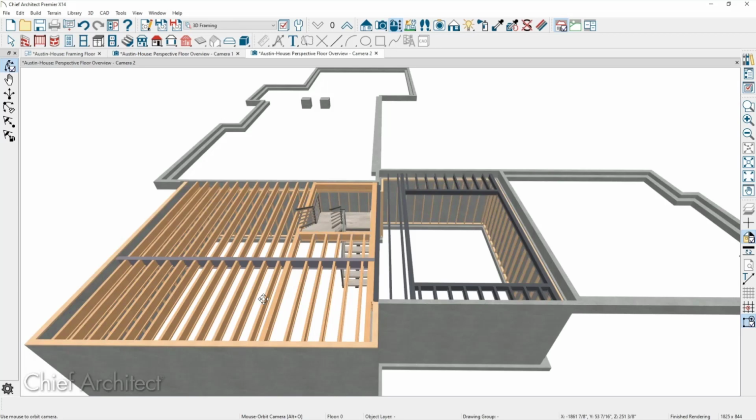And when you build your foundation with piers, once you've set the dimensional heights of those, I usually just use the copy tool because they've come in at the right elevation. And if you need to modify them based on terrain differences, you can click on them in an elevation view and adjust them.